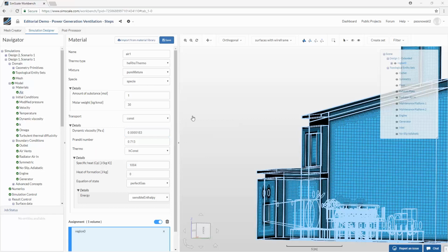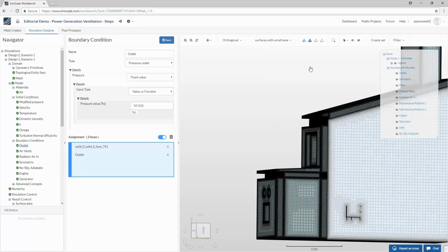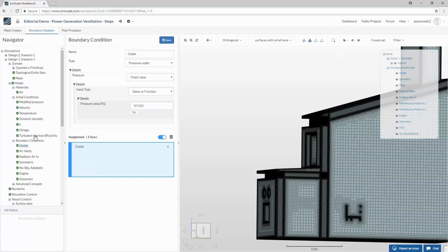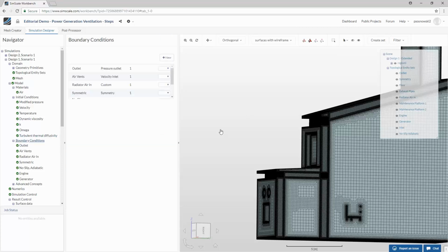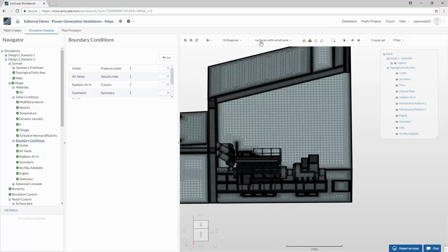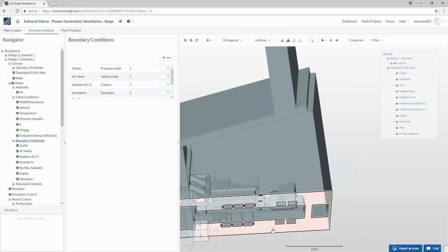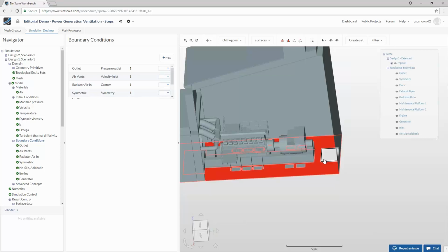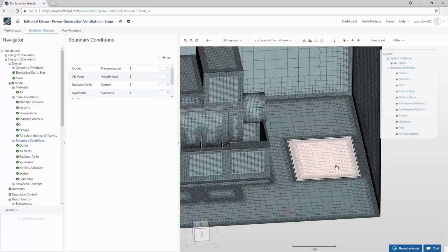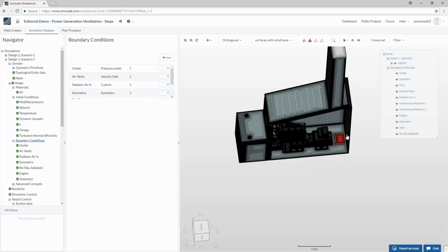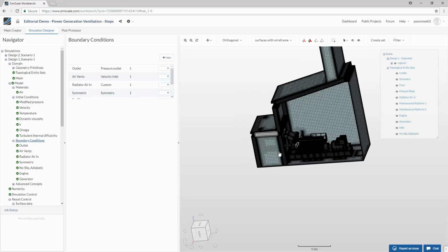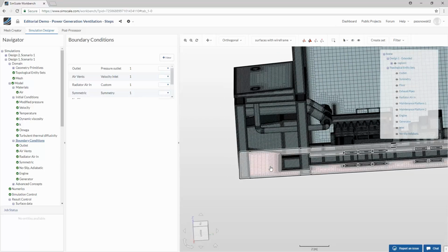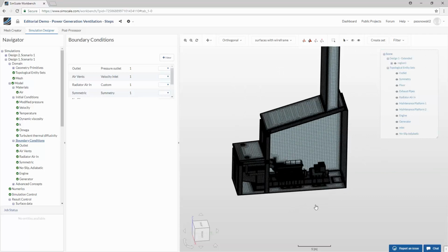The next question is, how do we position the ventilator locations? Well, of course, you already have some information about this when you're designing the facility. So I would know from the design that was given by an architect or another engineer that says, hey, I want to have the inlets here. That's my idea. And we take this from the experience of the designer himself. And then I would simulate it and say, okay, look, this particular tile that we have here, let me just get the surface with wireframe. So this particular tile blows cold air into the room, but everything is immediately taken out through the outlet. It makes no sense. So let's take it out, let's make it smaller, and put another outlet somewhere here, maybe, in this area. This will be like the next iteration I would do for a problem like this. So the choice of the location is arbitrary.